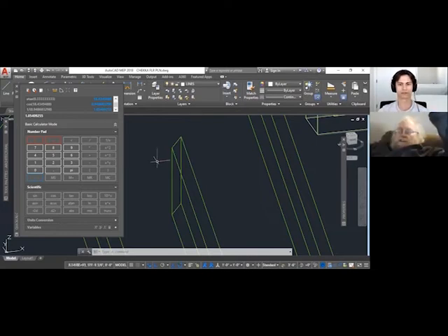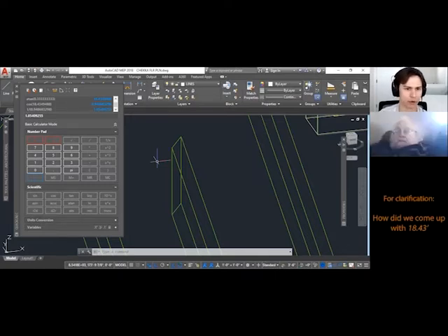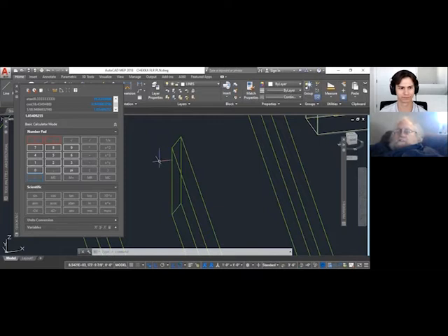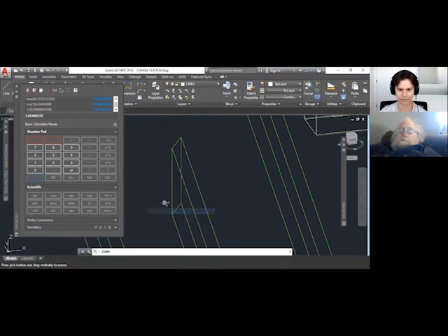Basically, you put a stair gauge on your framing square, one at 4 and one at 12, or 2 and 6, as long as it's the same ratio. And remind me again, 18.43 was the angle of what? It's the angle of slope of our 4 and 12 pitch. We determined that by taking tangent to the -1 power of 4 divided by 12. And then we came up with our secant, which is 1.054. And we're going to multiply the actual run.